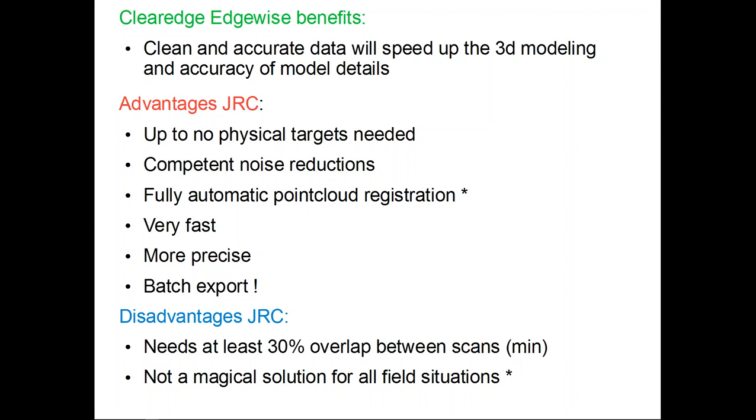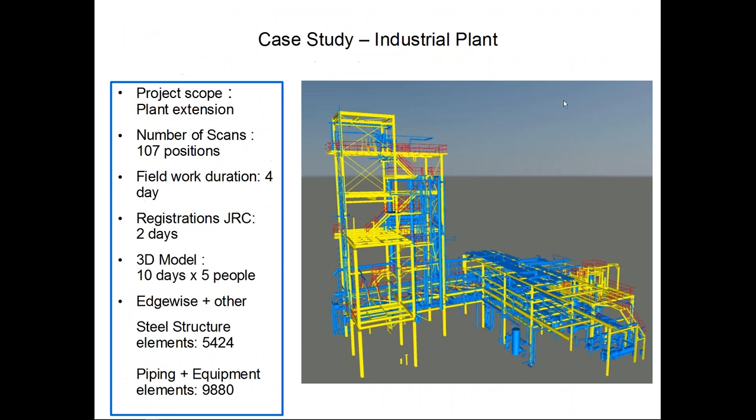It's a very fast software. For example, if one scan position will not be properly registered with the rest of the bunch, you can easily, with the tools inside the software, identify common points and then make a new bundle adjustment. But the second time you do a bundle adjustment, because the point clouds are already oriented, it is going to take very few iterations.